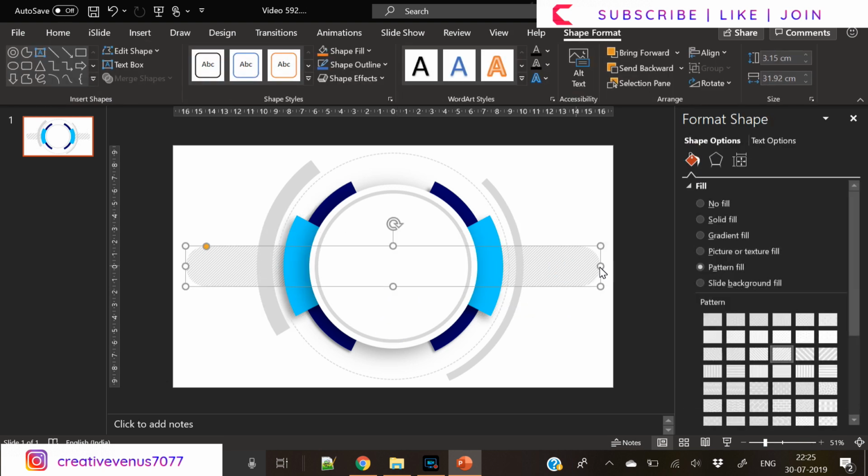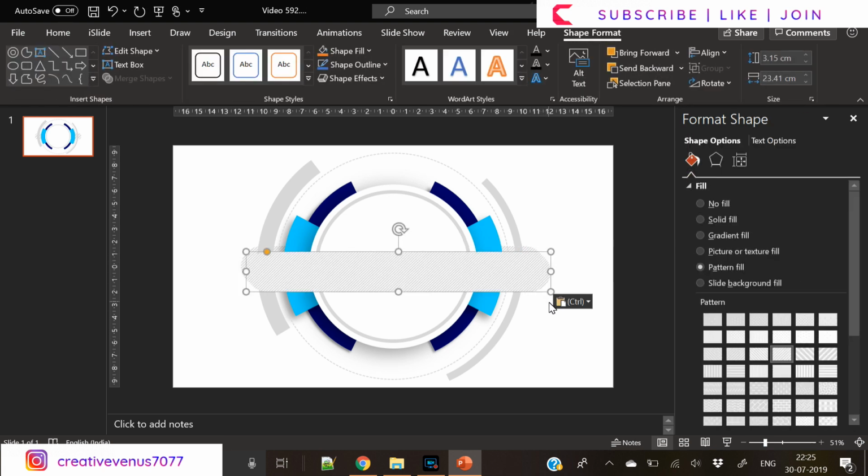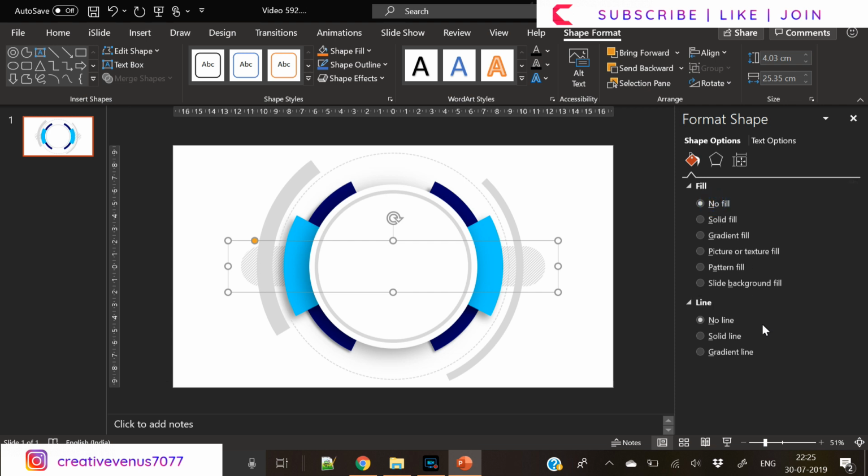So reduce the height of this pattern background shape and duplicate it. Slightly increase its height and width and remove its fill. So change fill to no fill for this duplicated shape. Send to back, select no fill, and we will only keep its solid line.